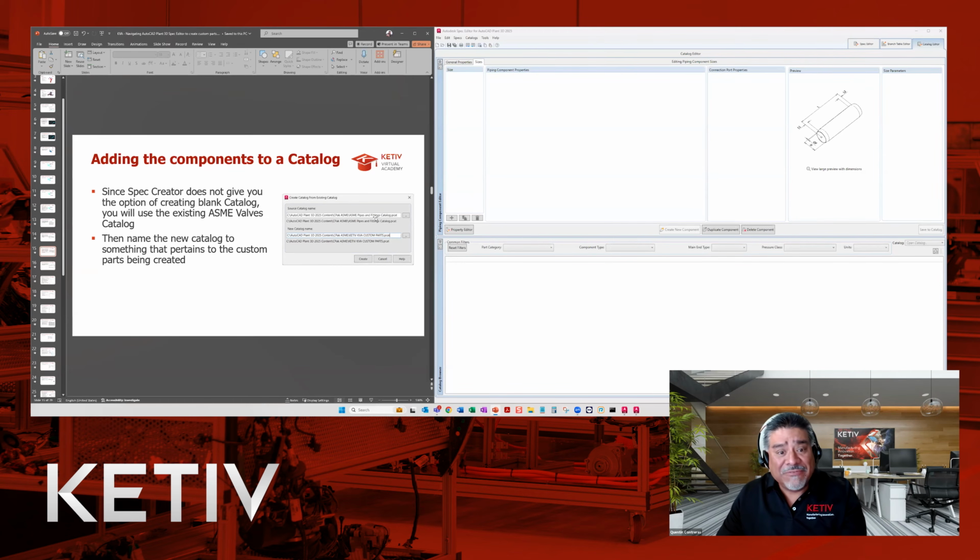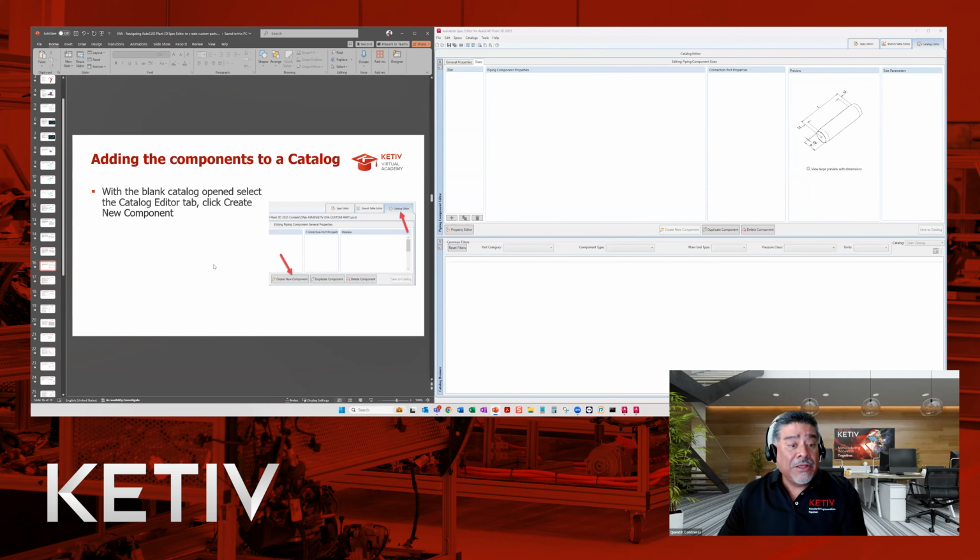So since I'm doing valves, I would create a copy from the pipes and fittings catalog that's already there. And then I'm going to give it a name that I want to call it for my catalog, whatever your naming convention might be for that. So once I do that, it would create that new catalog, but then I'd need to go in there and actually delete all the items.